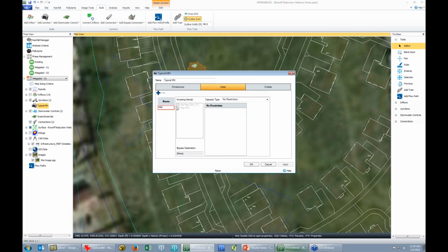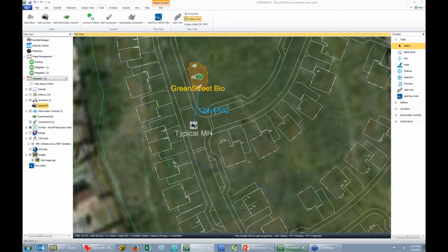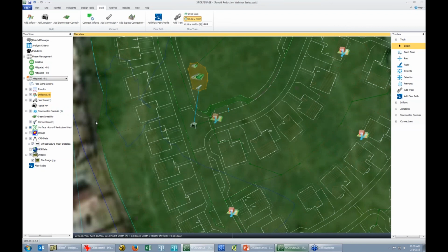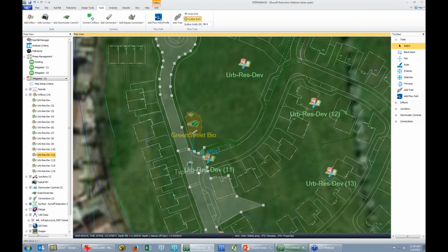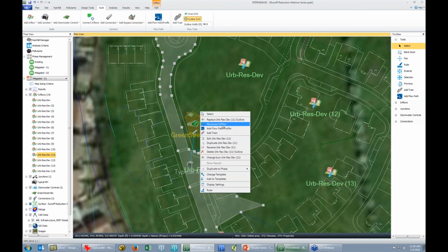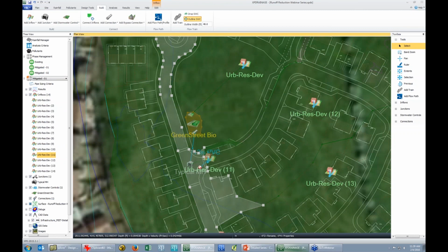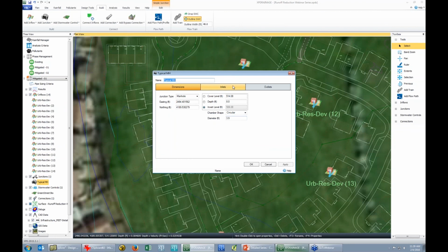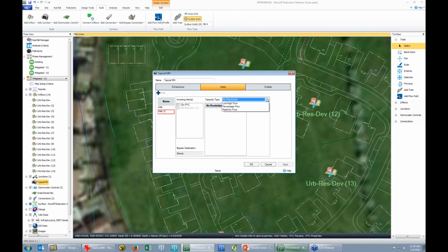So go to inlets, and I'll see that I happen to have an inlet, no restriction. Again, if I had flow from a catchment, let's say I have this inflow here, this whole area might drain into this manhole. Well, I could once again connect this into a new inlet. So now I have this inlet here. I could restrict that flow.